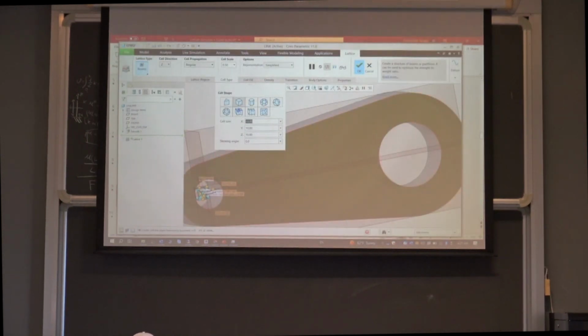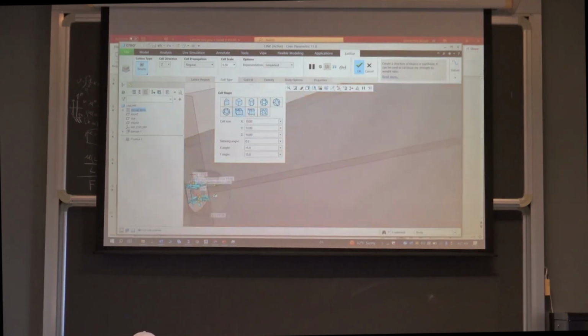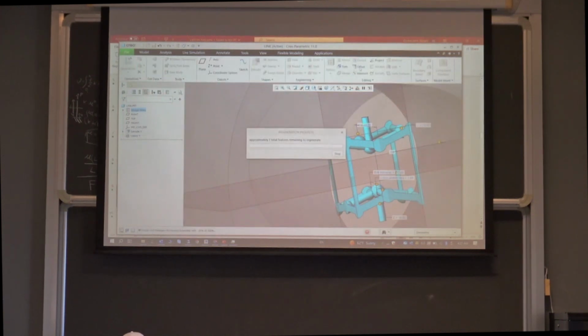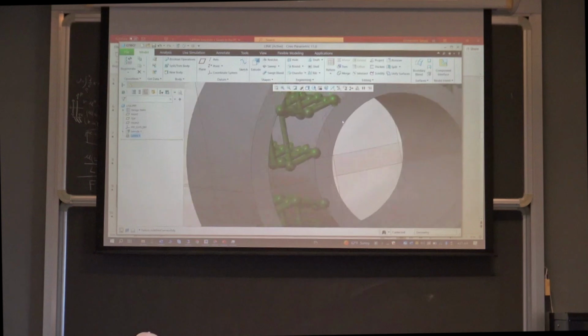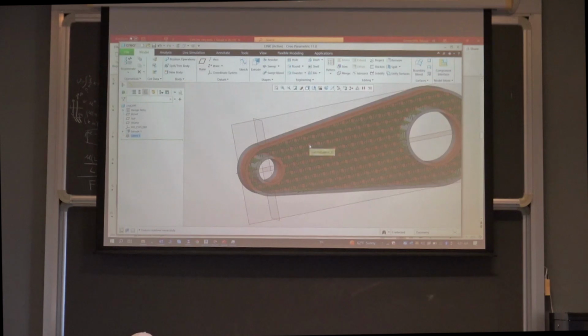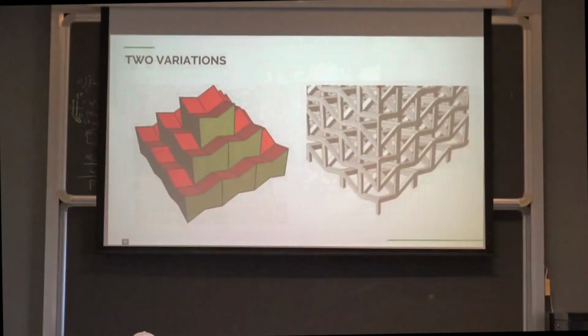So I go to Edit Definition again. This is our auxetic unit cell. So I can enter, for example, 5 degrees here. It's not symmetric anymore. Click OK. And we get this auxetic structure lattice. So this was the reason why we supported both options for auxetic. And yes, they are both auxetic. We checked it using simulation. So they're both auxetic, like here.